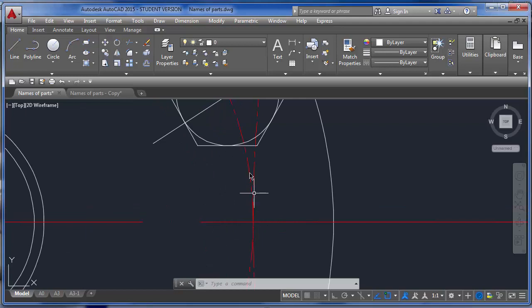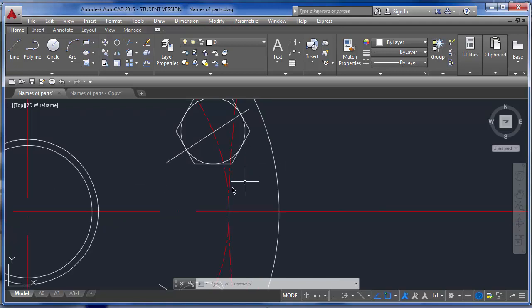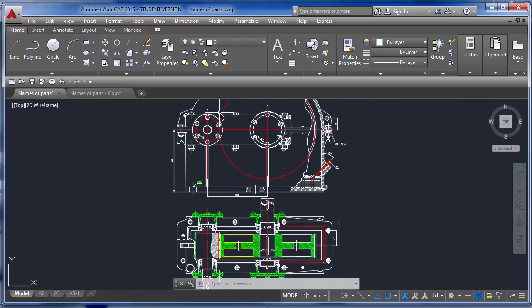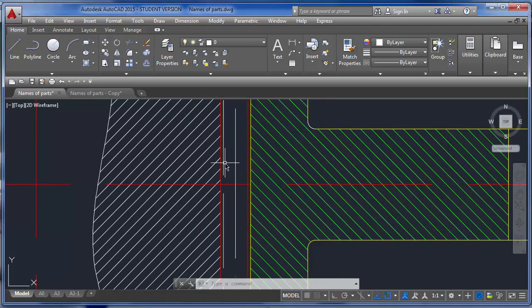The outer part is called the addendum, in a more technical way. So the addendum of the small gear will be visible, but the addendum of the big gear, I mean the driven gear, will be here, under, so we cannot see it from the top side, and it will be an invisible or dotted line.